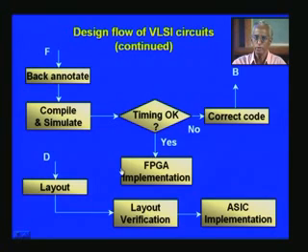And finally, you will have to make a hardware PCB, with this particular target FPGA that you have already designed using the whole design flow, and then you have to evolve a strategy for testing the PCB. After that you can integrate with this development system that we have, say that of Xilinx, and you can download your bit stream right onto the FPGA that is housed on the PCB that you have made.